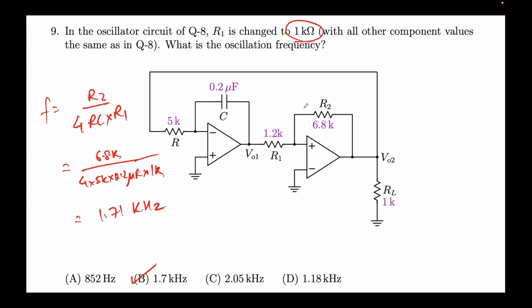All right. So what impact will changing this have? It will shift VTH and VTL. Remember, as we saw, the formula was VSAT R1 over R2, right? So this means the VSAT is shrinking. The VTL and VTH swings are shrinking. This means the Vout1 swing is shrinking, and hence you are switching faster essentially. So you see the frequency increases. Earlier it was 1.4, now it's 1.7.